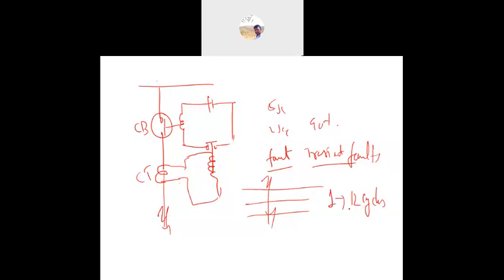Okay, so if the faults occur one at a time, the recloser for the first one should reclose after 12 cycles. After every transient, once the fault is cleared, it should reclose. And now the lines of 33 km.